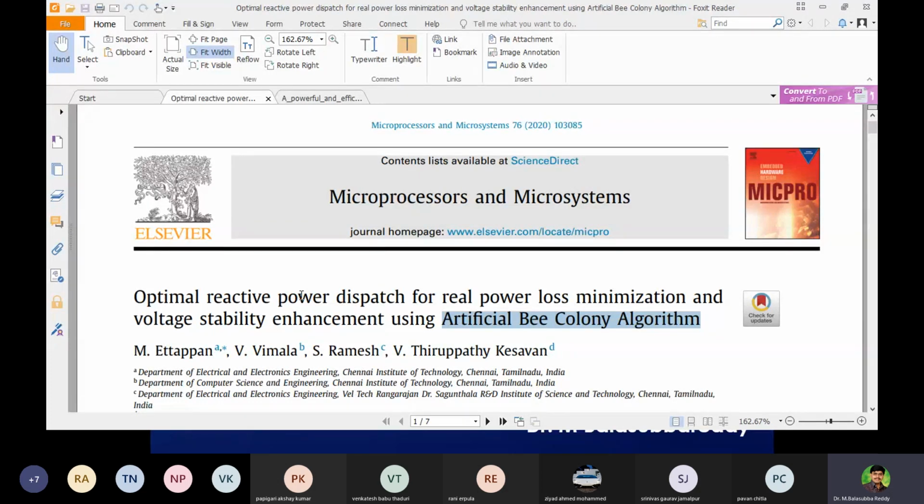So that is our expression to find the cost of the power. In that case, Ai, Bi, Ci are the constants of the particular generator, and PGi is going to vary, how much power is going to be generated in the particular unit.